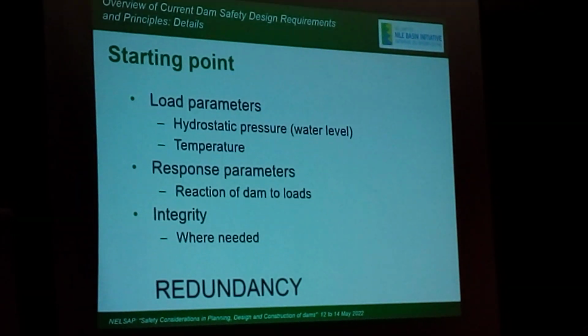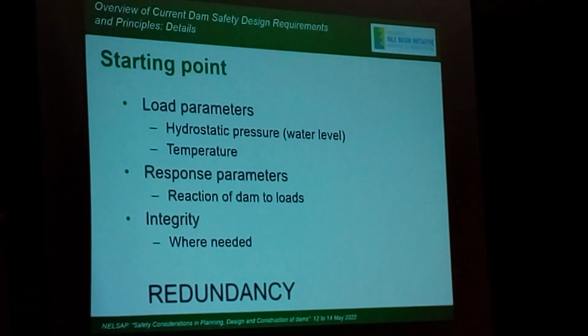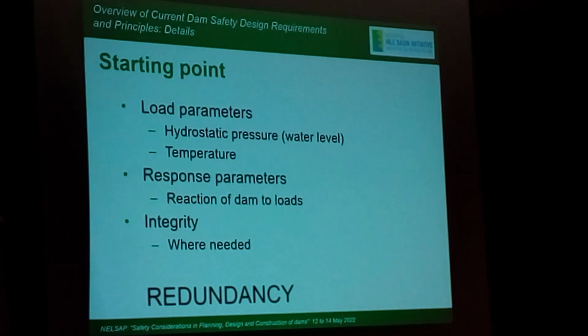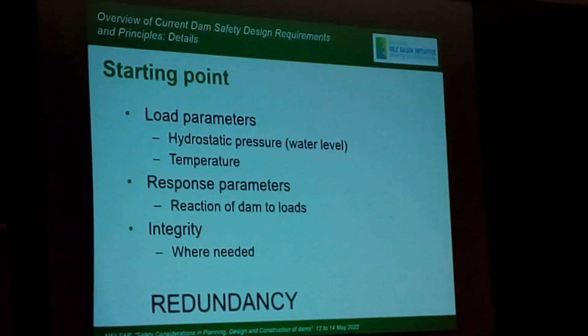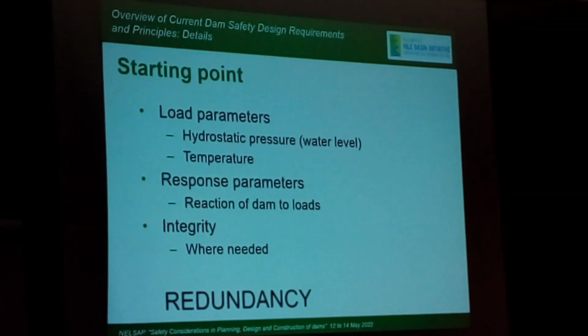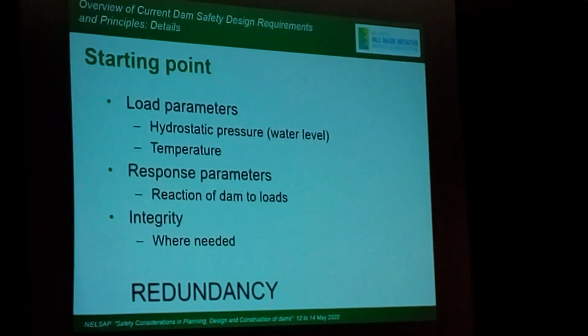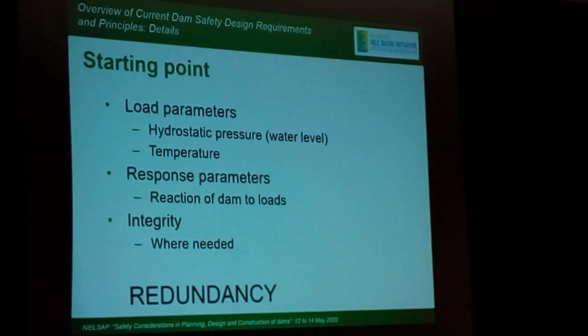So the starting point, if you do design, and we've talked a bit about it yesterday as well, but definitely water level in your reservoir. Starting point. And if you put in a system where you can do semi-continuous monitoring, say every 5 to 10 minutes, that you get the value of your water level, it is nearly as good as a gauging station.